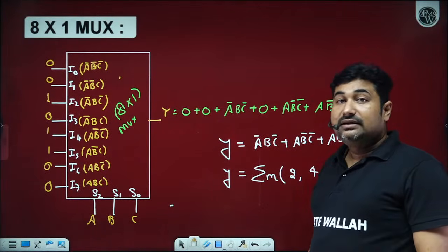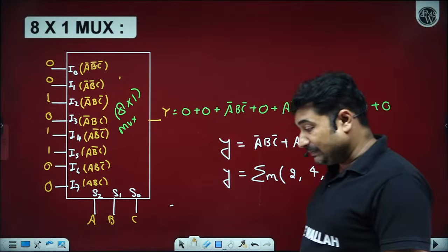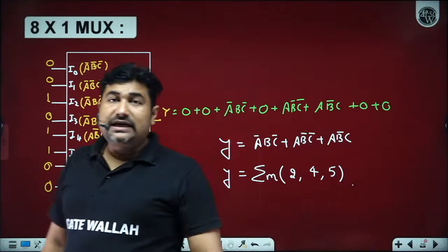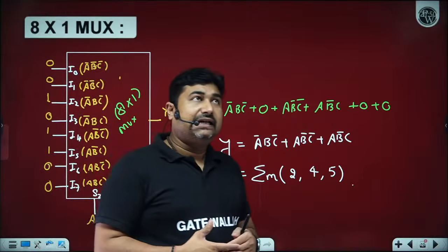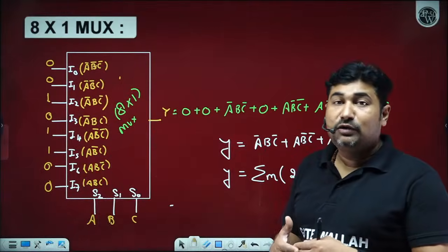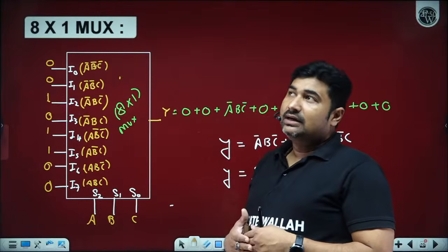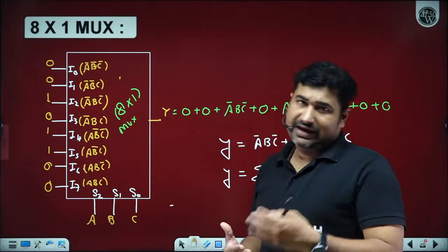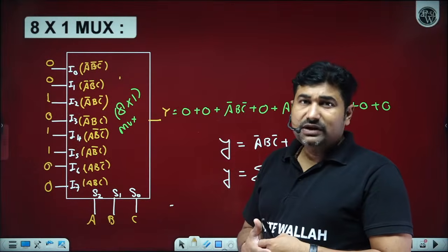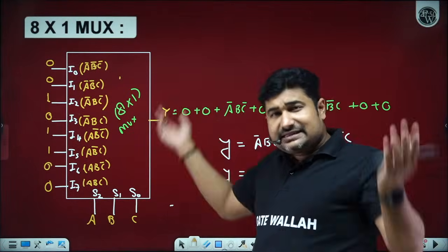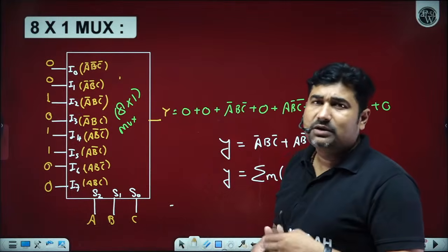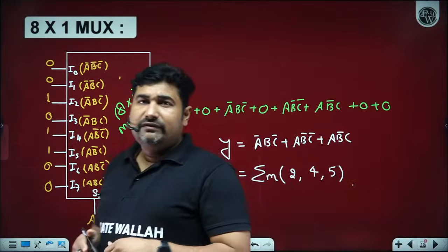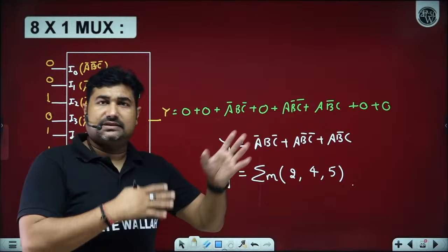But sir, we all know that the number of inputs to the AND gates will have some certain fixed amount depending upon the design of the AND gate with the logic family and fan in or fan out. So if we are thinking that we can design any size in the same manner, it will not go like that. We have to go with different logics.